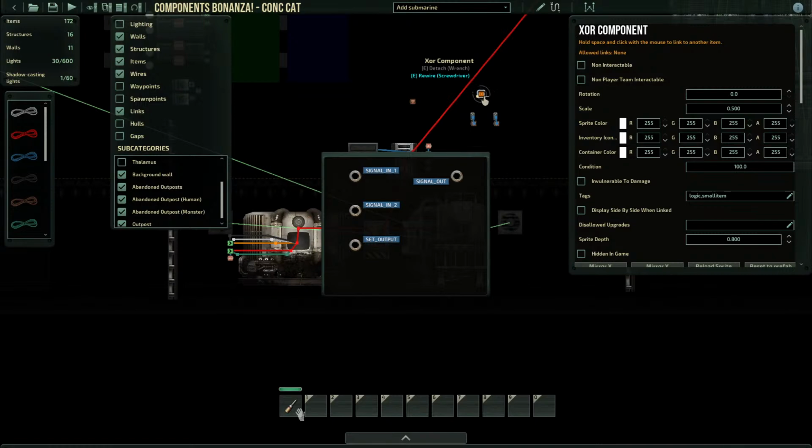That's the difference between the or and the exclusive or. The exclusive is exclusively or, never and. The or component is or one or two or both. Sorry, one or two or one and two. With the exclusive or, there's no and. It's either one or two. If there's both, there's no. It reverts back to its false condition output.